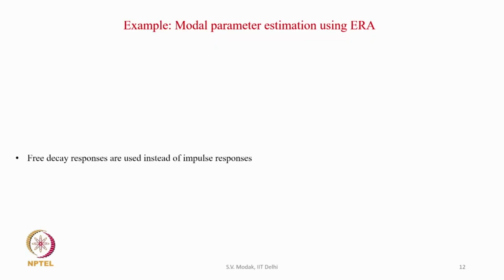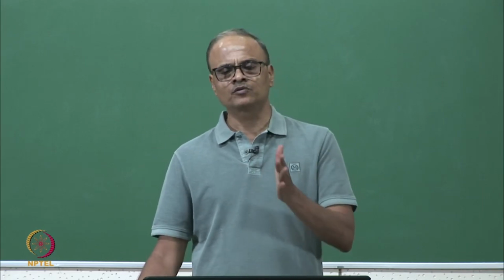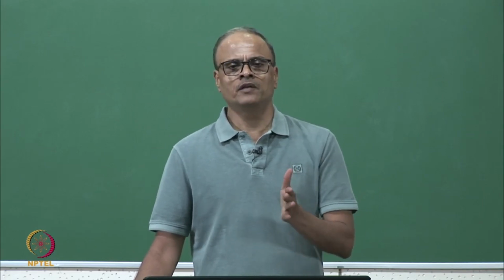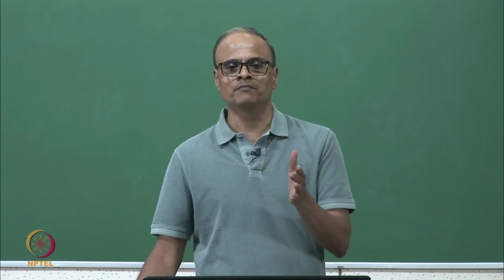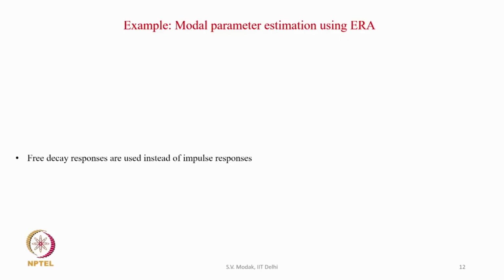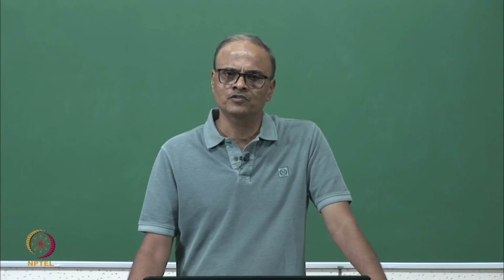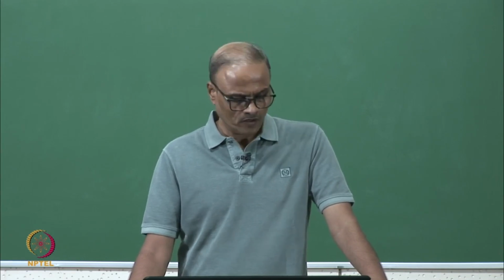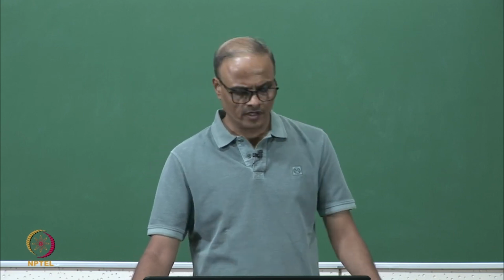Now here in this example we are going to make use of the free decay responses instead of the impulse responses. So, impulse response is also a free vibration response because we apply the impulse and the structure vibrates freely. Free decay responses are also free vibration responses, but they do not correspond only to the impulse being applied, they may correspond to other types of initial disturbances. So, this ERA can handle both types of free responses, whether they are impulse responses, or the free decay responses due to other types of excitations. Therefore, we are going to make use of the free decay responses in this example,